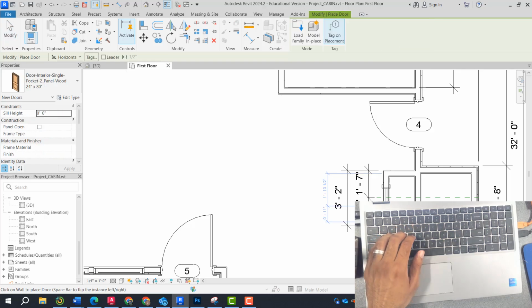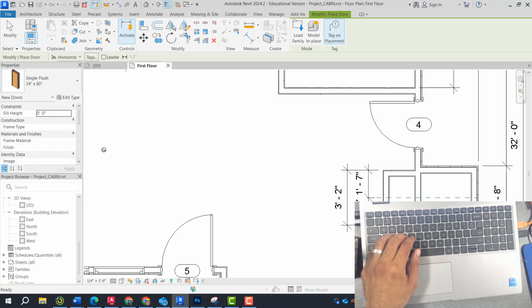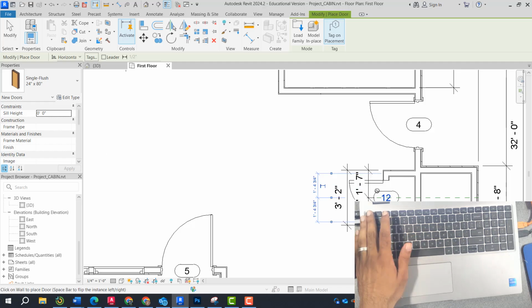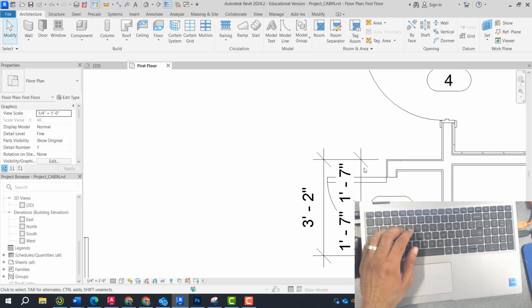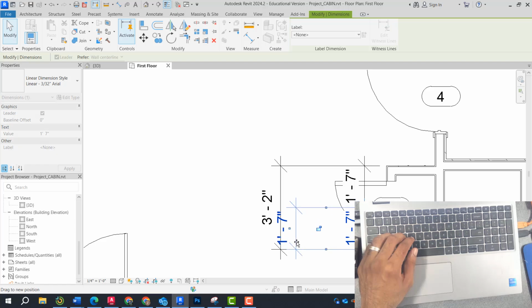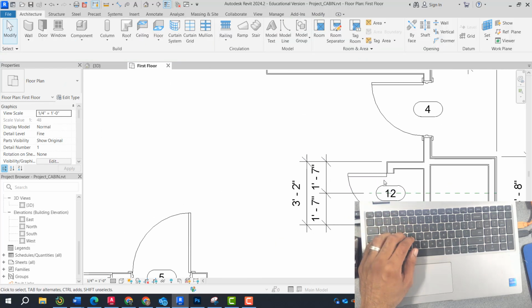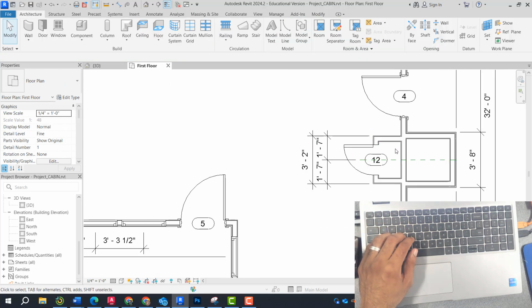I'm going to go under DR, and pick a 24-inch by 80-inch door that pretty much opens out. This door allows it to be a pantry that is more accessible. Again, I'm not a huge fan of bifold doors, and I knew I would alter the design of this cabin one way or another. So it starts now with this door.